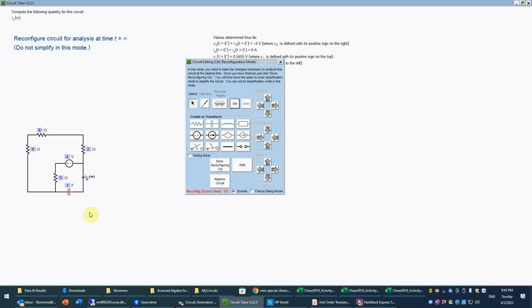Now, on the other hand, the capacitor in steady state, remember there the equation is the dual of the inductor equation, namely it's I equals C dV/dt. So the time derivative is once again 0 because we're in steady state. All time derivatives are 0 in steady state. And so now the capacitor is described by the fact that its current is 0. In other words, it's a zero valued current source.